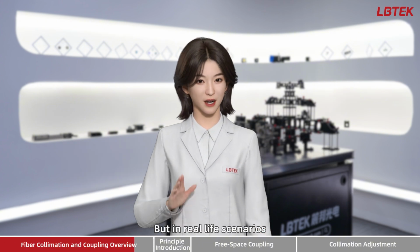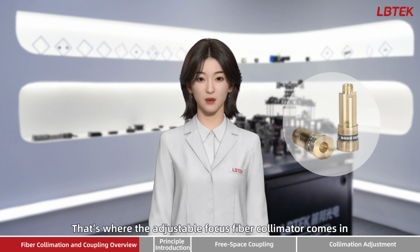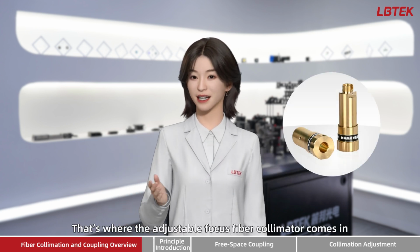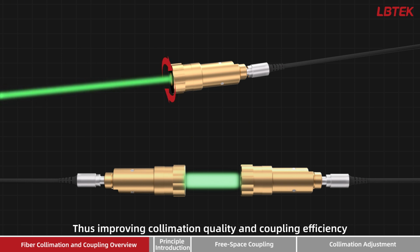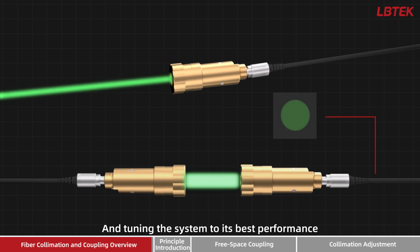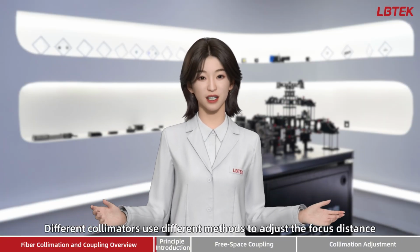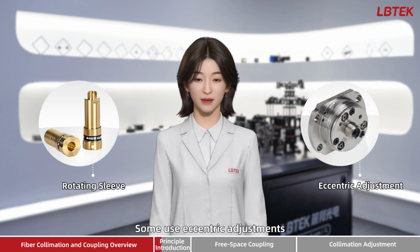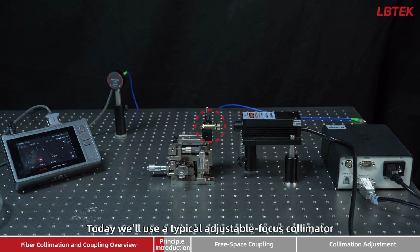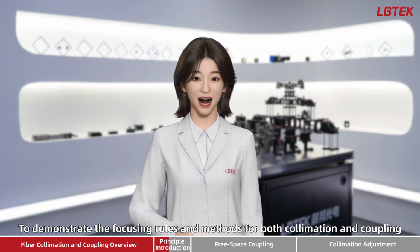But in real-life scenarios, the fiber often doesn't perfectly align with that fixed focal length. That's where the adjustable focus fiber collimator comes in. It lets you tweak the distance according to your actual light source wavelength, fiber type, etc., thus improving collimation quality and coupling efficiency and tuning the system to its best performance. Different collimators use different methods to adjust the focus distance. Some rotate a sleeve. Some use eccentric adjustments. Today we'll use a typical adjustable focus collimator to demonstrate the focusing rules and methods for both collimation and coupling.